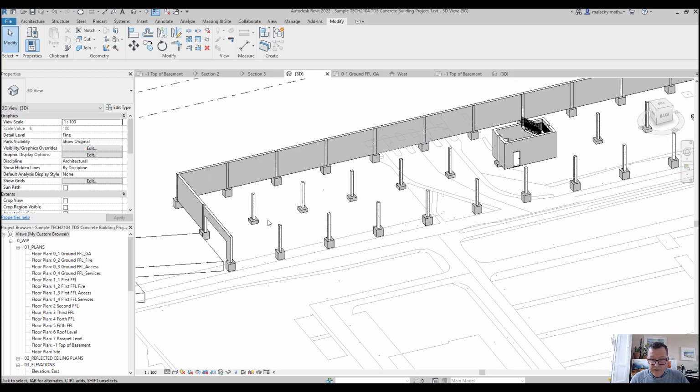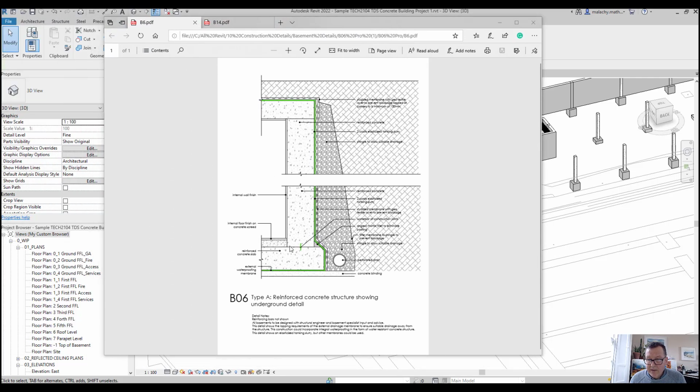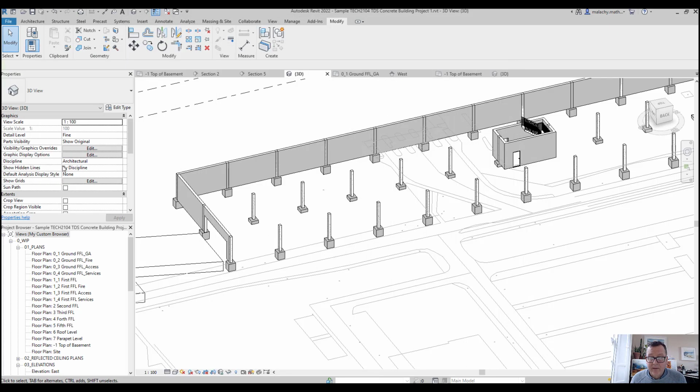You'll have done your own research on this, and you might try something that is slightly different. I'm basing my design on this detail here, something similar to that. So here's my concrete slab. In my case, I've decided just to deepen that into a ring beam because we've got 6 stories of point loads coming down here. And then we will create the walls in between the columns, which is this bit here. Here's all my tanking and everything else that needs to be done there, and then I'll be pouring a slab in on top of that here.